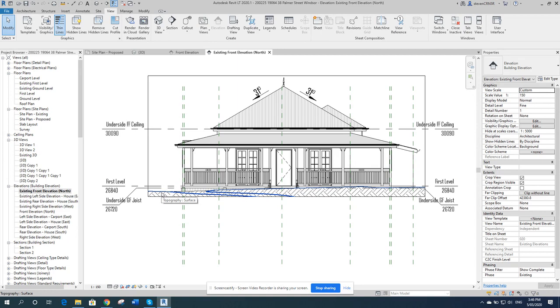So we have 2 sets of topography sitting in there, so one for existing and one for proposed, and then we hide them and demolish the topography or whatever to then in the proposed to be able to see the whole ground floor of the house if the house was raised. So we actually work backwards when we're doing that, when we raise a house.